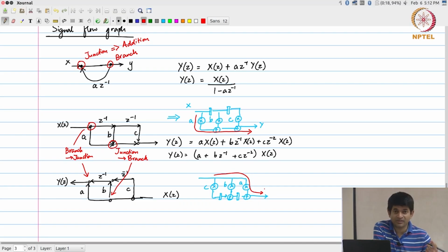So that's one very good point, right? Essentially what is being said is, the x over here will be some number of bits. If this is some n bits, then this will also be n bits, this will also be n bits. But the moment I multiply an n bit value with something else, the number of bits that I actually need in order to represent the result is more than n.